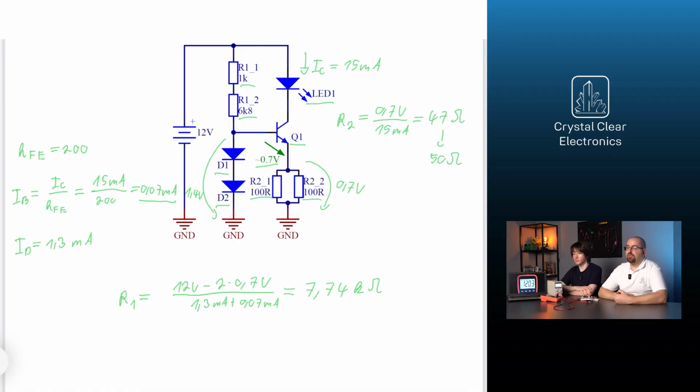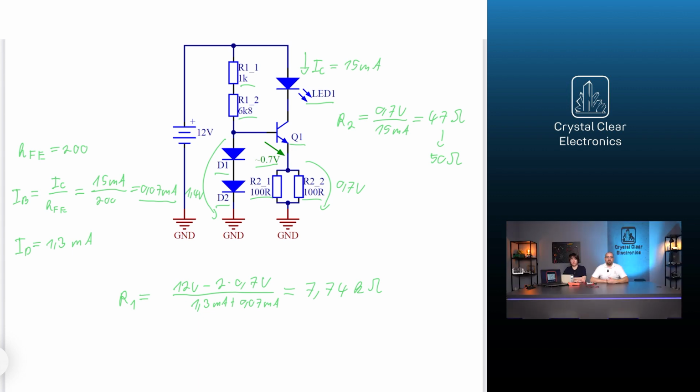Of course, you can't connect an infinite number of LEDs in series, since the sum of the voltages across the load, the 50 ohm resistors, and the transistor's collector-emitter voltage cannot be higher than the supply voltage. In other words, the circuit can only maintain the desired current value as long as the transistor voltage is higher than its saturation voltage, which for this transistor is around 1 volt. So, as a rule of thumb, the supply voltage should always be slightly higher than the voltage across the load.